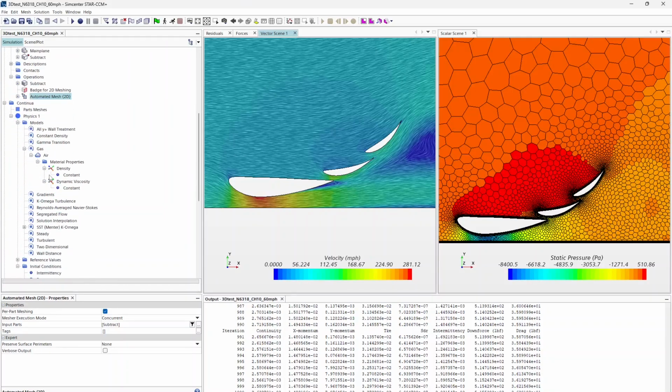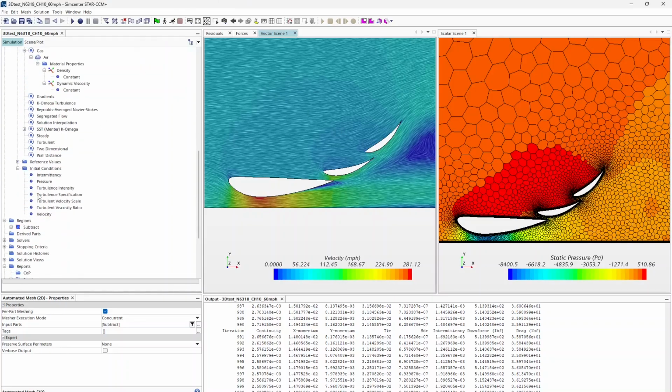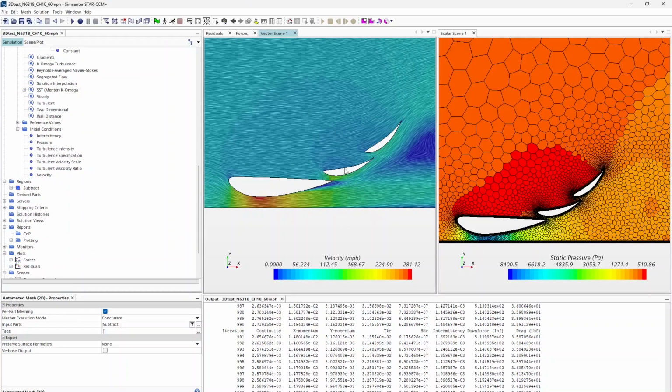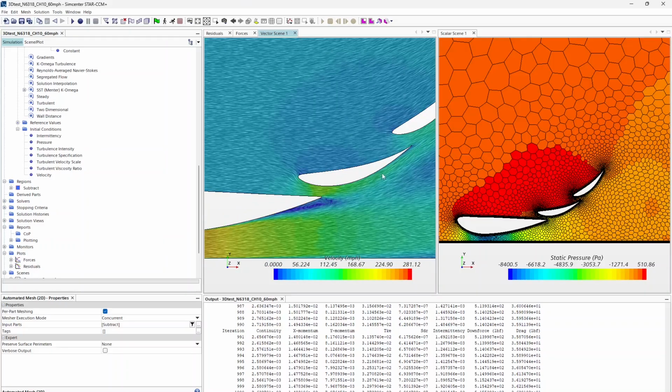But for now, this is a DRS system, right, or an active aero system. We want to move these two flaps into a different configuration where they aren't twisted so sharply, so that the air can pass through it easily. We'll drop downforce, but we'll drop drag, which will be great for the straights. And then we can move our airfoils back to this closed position for our turns when we want more downforce. And so we can model, we want to not only just rotate these though at any arbitrary location.